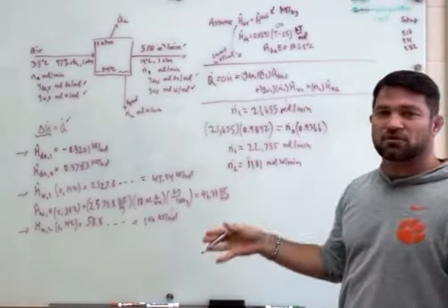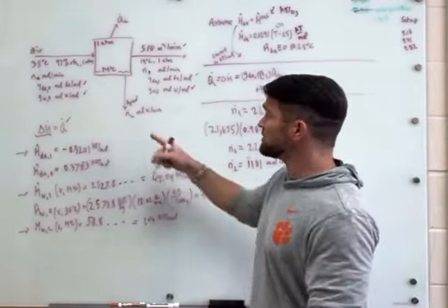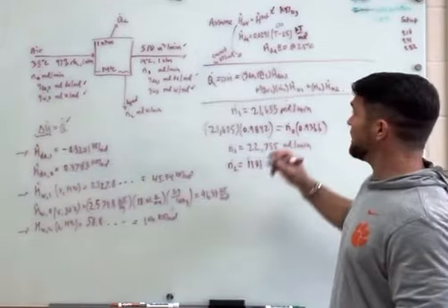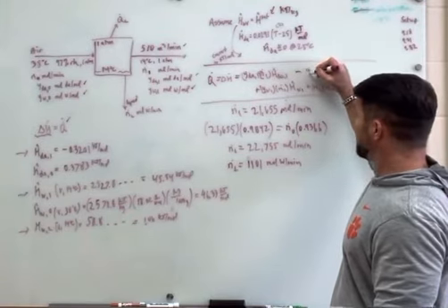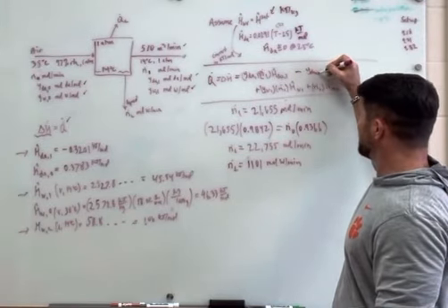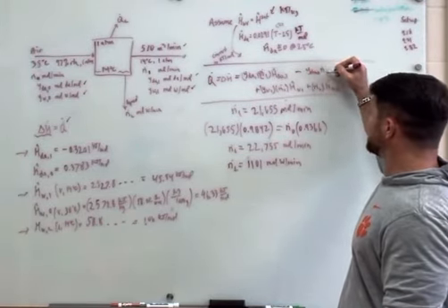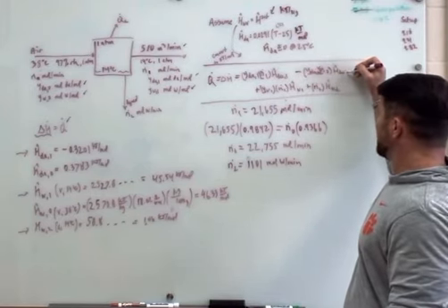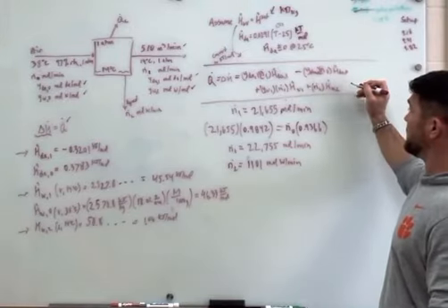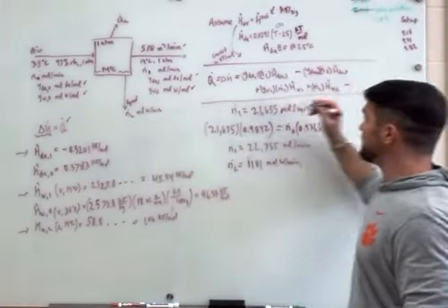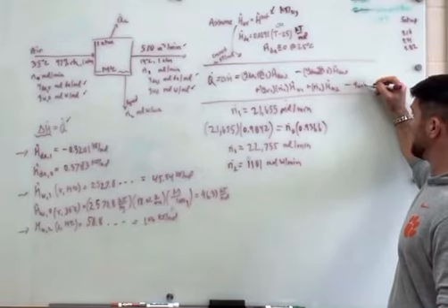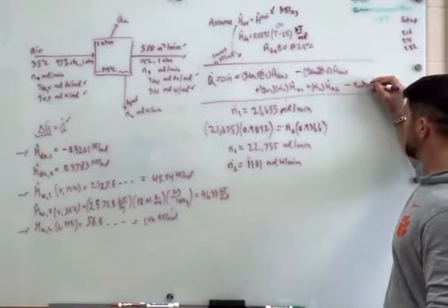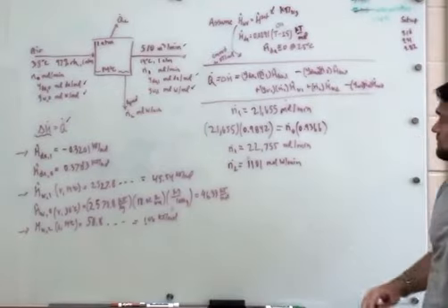And now I have to subtract all of the species coming in. So I have the air coming in, so it's going to be composition times the total moles times the enthalpy. So minus y_dA0 N0 times H dry air 0. And then also I have water in this stream, so I have minus y_W0 N0 H water 0 entering.